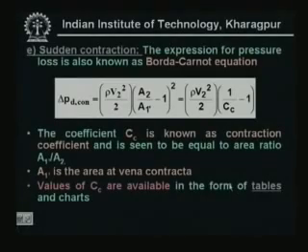Again, as I said, this Borda-Carnot equation is an analytical equation. If you use the right value of the contraction coefficient, which is obtained from experiments, then you can use the Borda-Carnot equation for estimating the dynamic pressure loss due to sudden contractions.